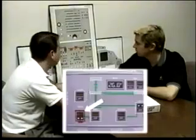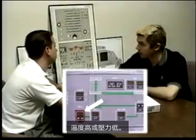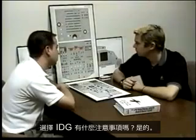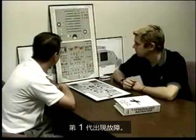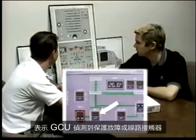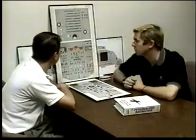Fault in IDG. IDG fault means that the IDG oil temperature is high or the oil pressure is low. Any cautions to selecting an IDG? Yeah, don't press it for more than 3 seconds, and don't press it if the engine's not turning. Fault on Gen 1 indicates that the GCU has detected a protection fault, or the line contactor is not closed and the switch has commanded it to close.